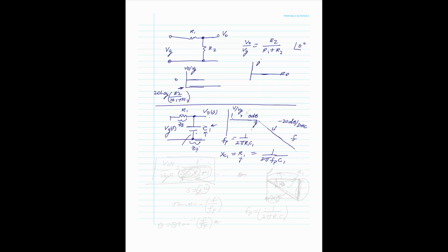Now, what is the circuit that's associated with this pole? Immediately when you see this single pole, you just draw the gain is 1, that's the K, and this is 1 over (sC1R1 plus 1). That's the transfer function. There it is, the output to input transfer function. That is exactly this. You could see at low frequency when s is 0, it's 1. That's here, which is, of course, 0 dB when I use 20 log on both sides.